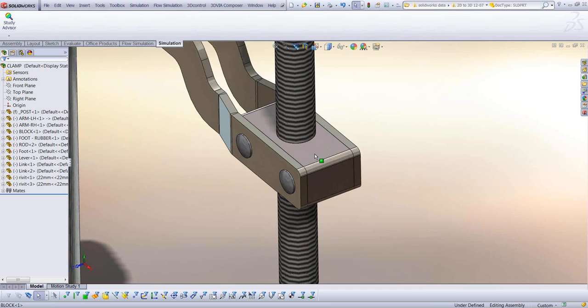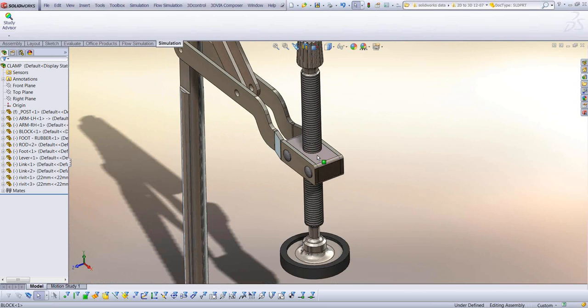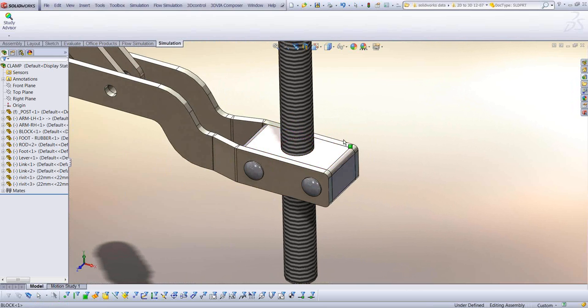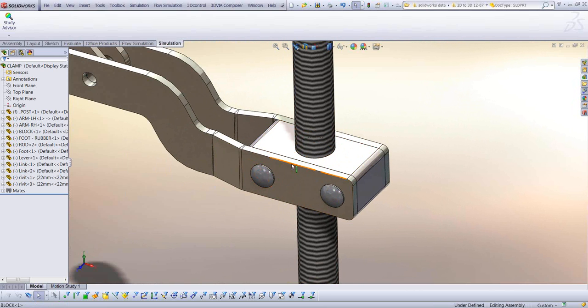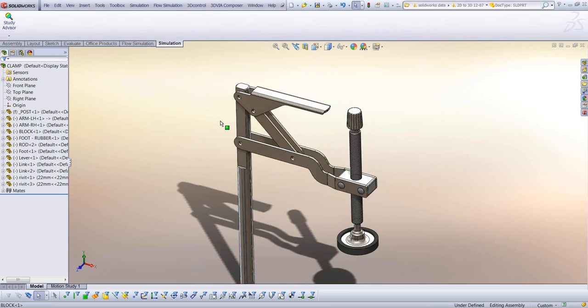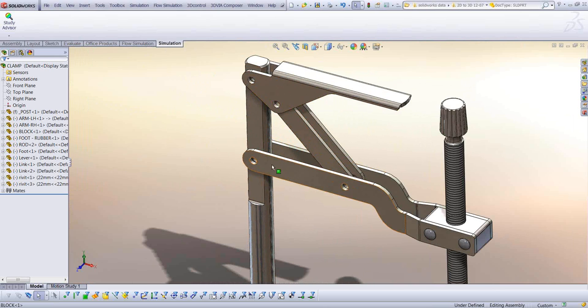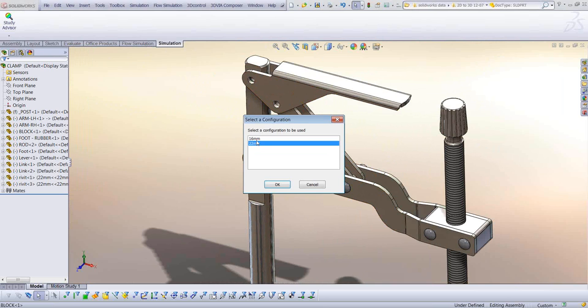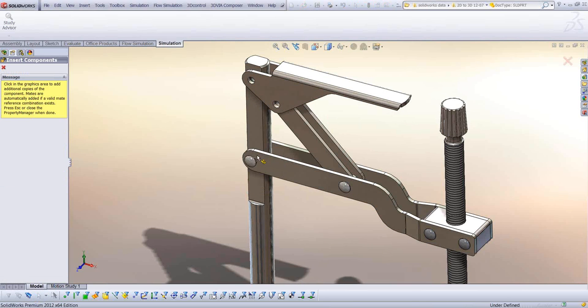So this is SolidWorks working at its best. It will automatically figure out the right mates, the concentric mate, as well as the coincident mate for you. So quite a powerful feature. It saves a lot of time. And for the rest of the 4 holes, I need a 16 millimeter rivet. So again, I'm going to do a drag and drop operation here, and this time I'll select 16 millimeters.